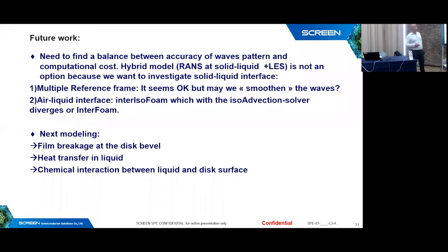Future work: we need to find a balance between the accuracy of the wave pattern and the computational cost. Unfortunately for us, we cannot work with a hybrid model, using RANS at the solid-liquid interface and LES outside, because we also want to check the solid-liquid interface, since I showed you that the collapse patterns are really interesting for us. So what we want to do next is to check the MRF.